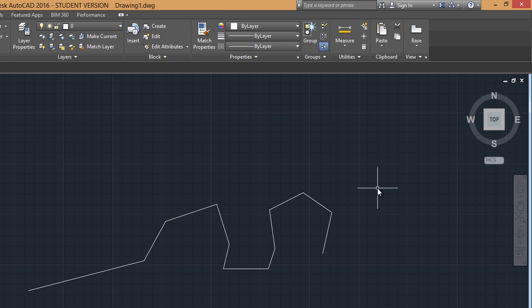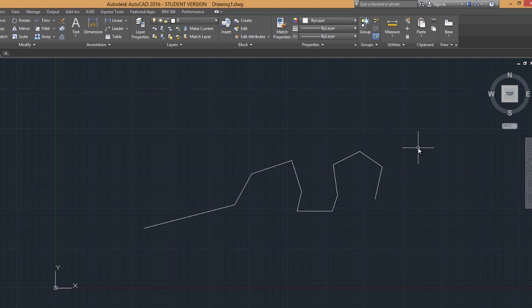So the cursor changes back to its default appearance, and in the command window, the only message displayed is command, and as it is grayed out, it says type a command, meaning that AutoCAD is waiting for a new command. So this is a very typical process of the command structure in AutoCAD. It's also the quote-unquote language that AutoCAD will speak with all the commands. And once you've gotten used to this, mastering new commands will come more quickly and easily, because you'll find that AutoCAD tends to stick to this language. So in short, you first select your command, then the locations, and then you can hit escape to exit. So note that escape also aborts all commands at any given time.